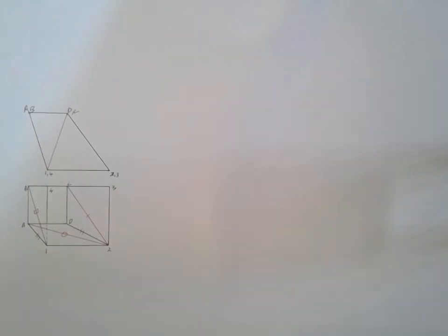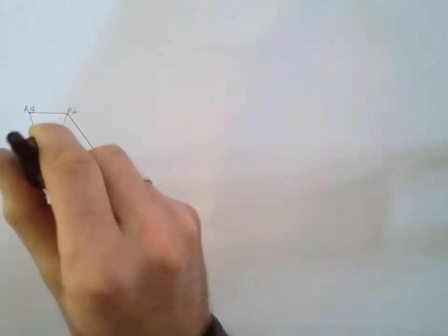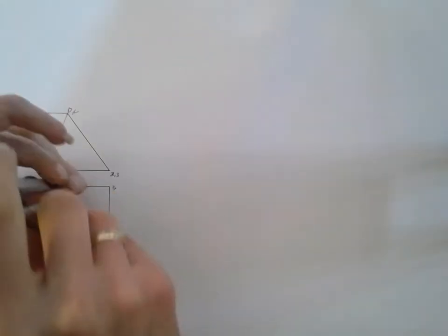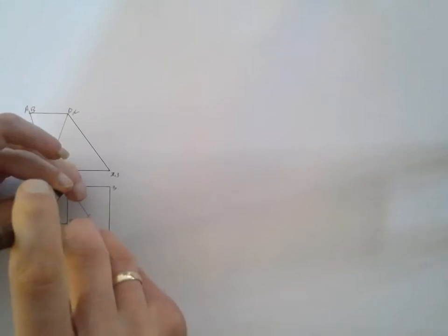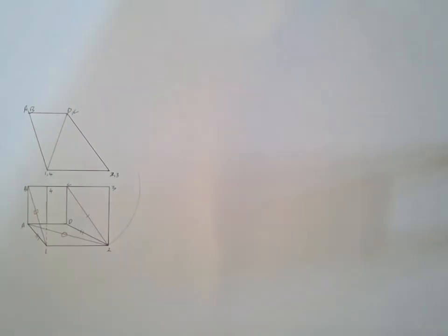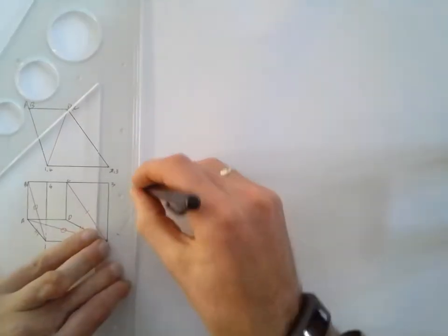Then our true lengths, using your compass, I'm going to start with the true length of C2, the one that I've marked off with a single line. Take my compass, I'm going to place it onto a top point, so there, point C, and I'm going to open it up to point 2, and I'm going to draw an arc. Okay, in this case upwards, and then take the edge of that arc and project it into the front view.